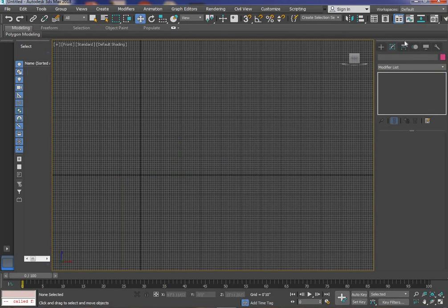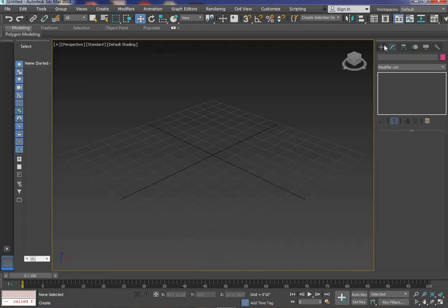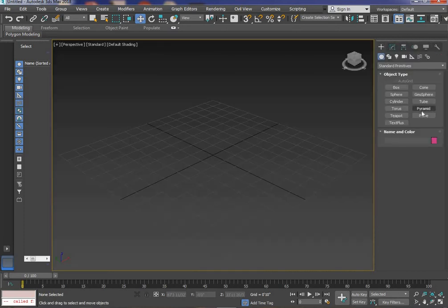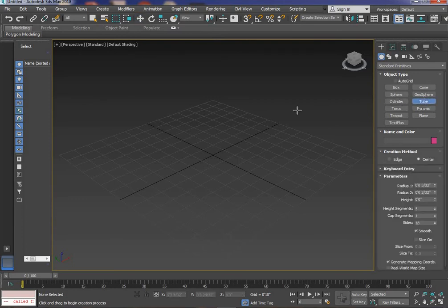Then the last option we have is FFD cylinder. Here I will use some cylindrical shapes. For example you can use it for pot design, like a flower pot. If you want a pot, then you have to use the tube option, because you need an open portion in the middle. If we use cylinder, then we will not get the hollow portion inside. It will be solid. That's why I am taking the tube here.